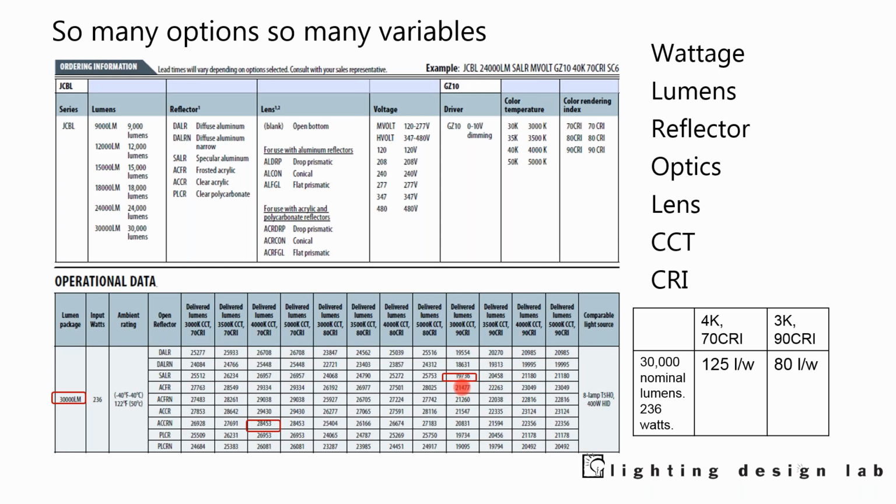And we go all the way over to here where we have 19,700, almost 20,000 lumens. So that's a significant difference. We go from almost 30,000 down to 20,000 lumens for the same fixture type. Here it's 3,000 kelvins, 90 CRI. Maybe I'm putting these lights in a food court at a college, or an airport concourse, or a high lobby in an industrial facility where color rendering is important. Or it's a big box retail store, Target or something.